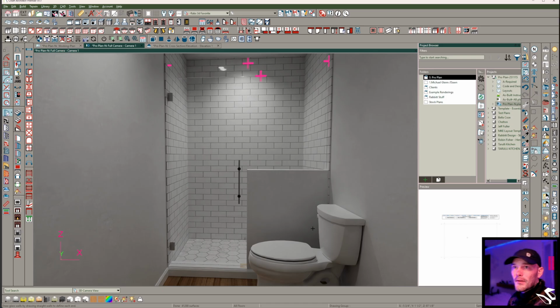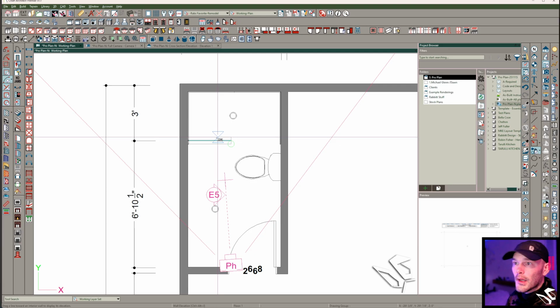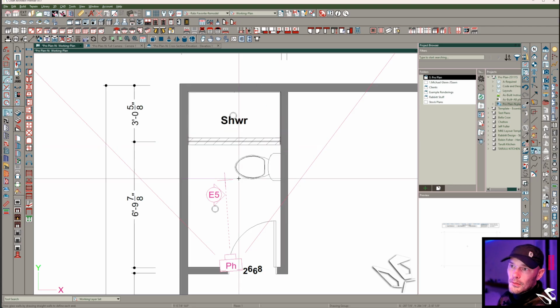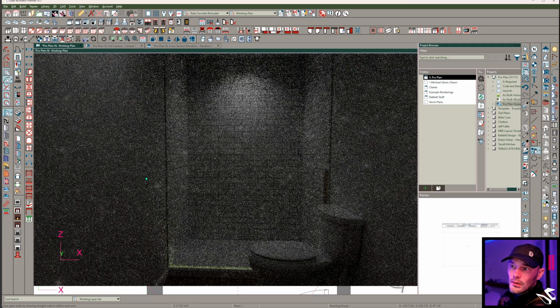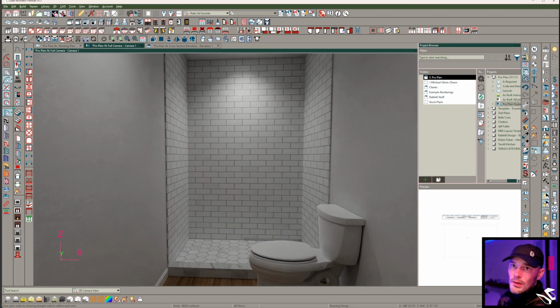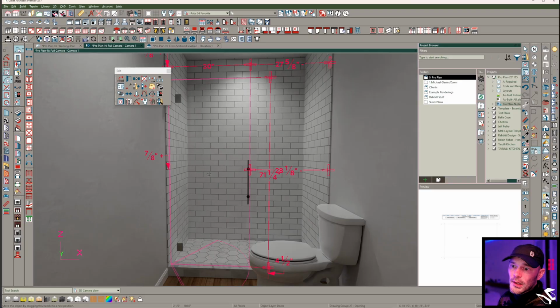That way, if I just draw with that from the beginning, so let me get rid of this wall and this wall. If I just draw from what I've created as a default in my template, now I'm just drawing with this wall assembly. So if we go look in a 3D view, this is what I'm drawing with, this is what I've got, right? And so then if I use that same default doorway and I press that tool, activate it, place it, there we go. It's cutting perfectly into that assembly, all right?